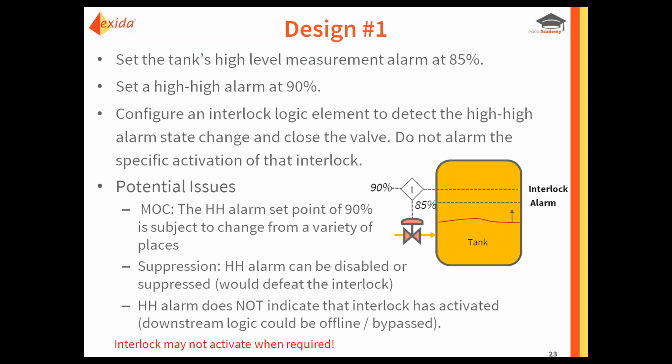So depending upon the importance of the interlock, you might want to think about redesigning if you've done it this way. Or make sure that you have rigorous management of change processes in place to make sure that items like changing the limit or disabling the alarm cannot happen. That would be what you would need to do to make that a viable technique.